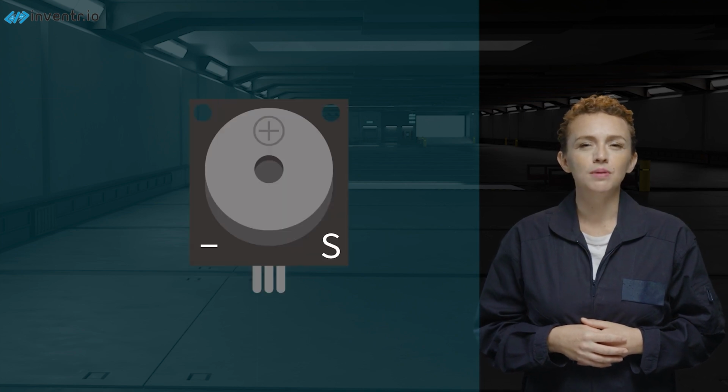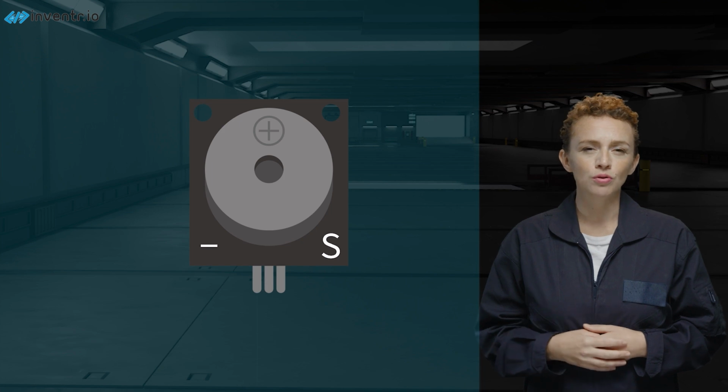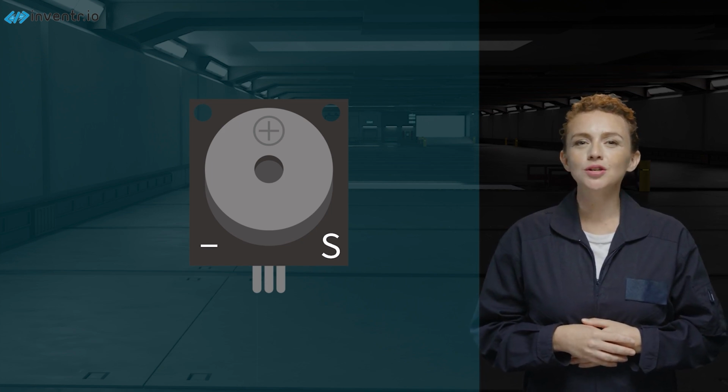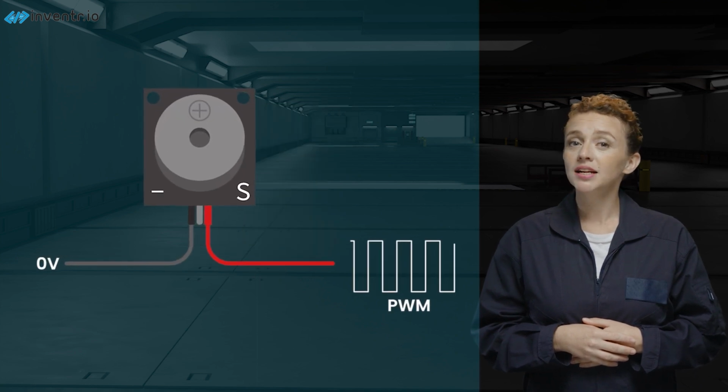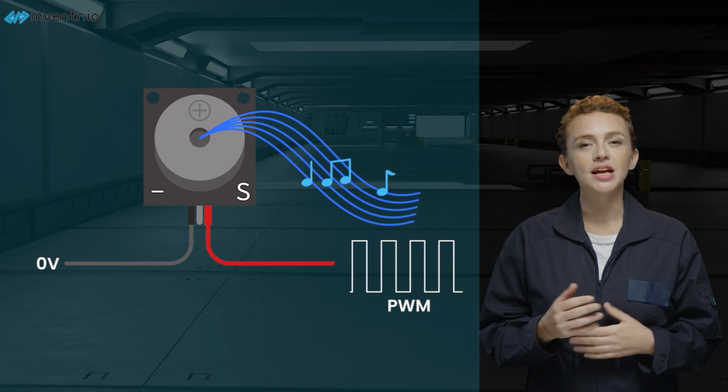Let's talk about our new comrade in arms, the passive buzzer. This small, usually cylindrical component is capable of generating a range of sound frequencies. It's like a tiny speaker that you can program. In the electrical universe, the passive buzzer is a piezoelectric device. When an oscillating electrical signal is applied to its terminals, it vibrates and creates sound.